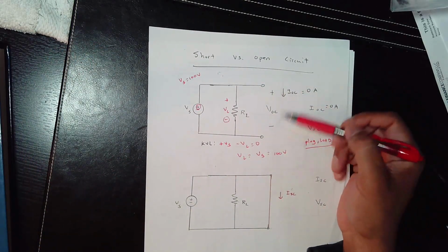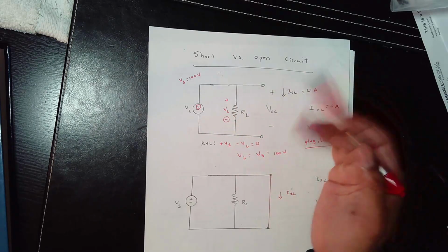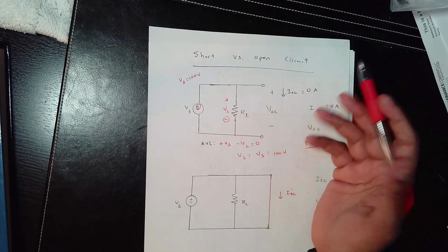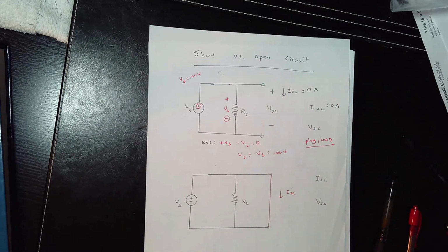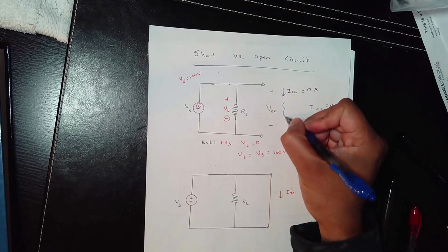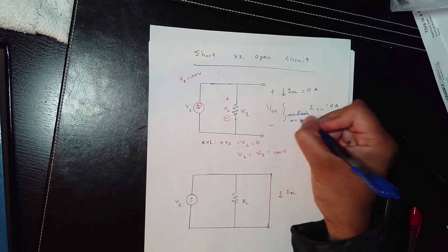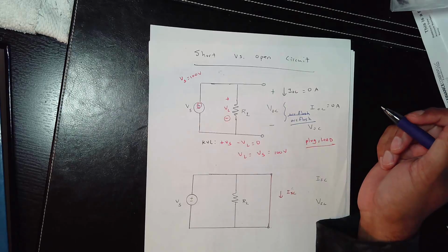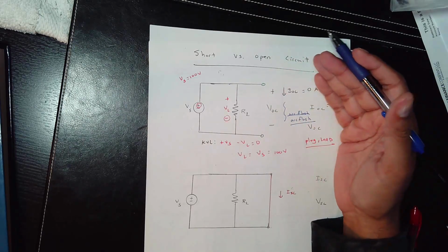Now, what are the bad things about this? Well, if it's a wide open circuit, and let's say this is something small. But let's just say this is like, I don't know, 40,000 volts, right? So what you're going to create here is an arc flash. At a high voltage, it'll create what you call an arc flash. Let me write it again, arc flash, okay? And that is not good. So in any of these high voltage areas, you want to wear protection. So this is actually very dangerous, okay?